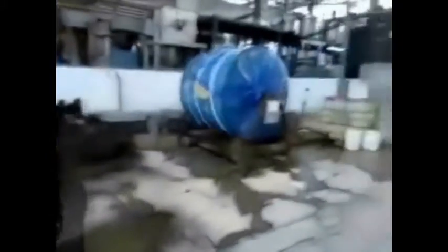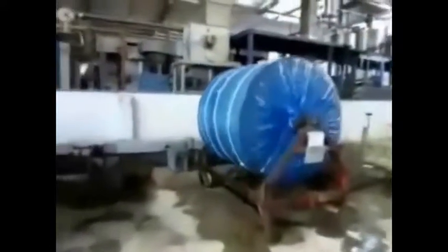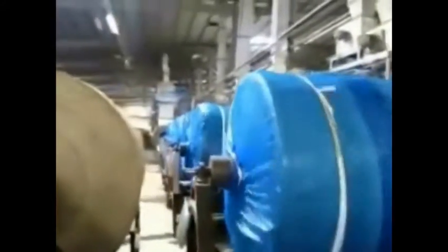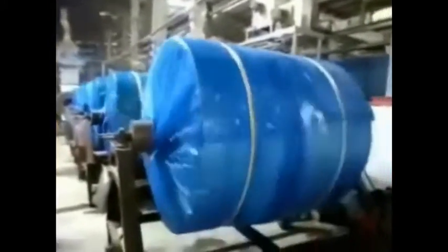Batching. It is also known as the conditioning of the fabric. After singeing or polishing, the fabrics are allowed to condition with hydrochloric acid or sulfuric acid for 8 hours, including a rotating motion, where the fabrics are kept packed in airtight polythene. The conditioning time or chemicals used depend on the fabric or fiber composition.